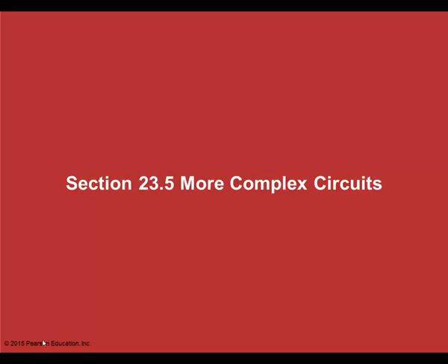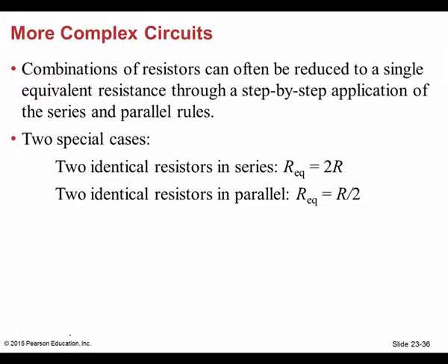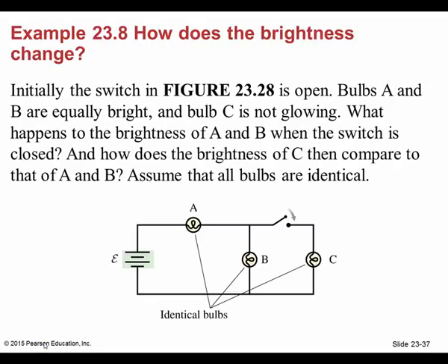All right. Okay, complex circuits. Now, when we look at more complex circuits, basically, what are they talking about? Well, when you get into combinations of, for example, here we have 2 in parallel and 1 in series, okay? And so you say, well, how would I solve that circuit? Well, you got to realize something. And you say, well, how do you know if it's in series or parallel? Look, you got a single pathway here, but you've got alternate pathways here and here, okay?